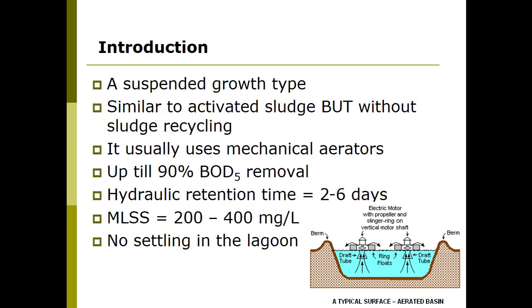Also, here there is no settling in the lagoon. If you remember, in the WSP, the waste stabilization pond, the pond is divided into 3 zones. But here in the suspended growth type, in the aerated lagoons, the whole lagoon is considered as one zone. There is no settling, because of the aeration and the turbulent mixing applied in the lagoon to mix the organic content with the biological creatures.